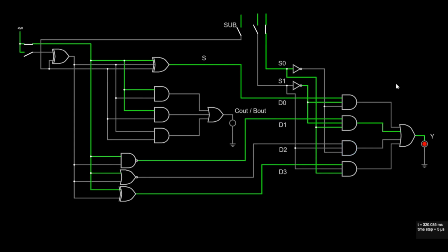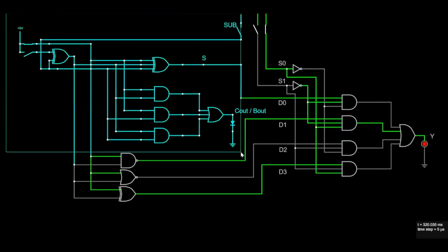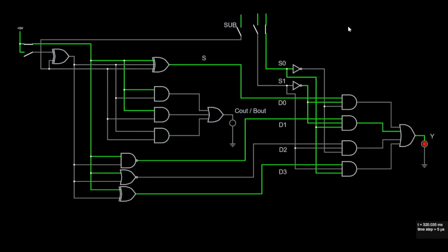And so we've seen some of these elements before, for those of us that are perceptive. We have a multiplexer over here, right? A 4-to-1 multiplexer. We have 4 data lines, one output. So we have a multiplexer. Big whoop, right? We've seen that before. We actually also have a full adder subtractor circuit right here. That's another thing we have. Isn't that crazy? The only thing we haven't seen is this circuit in this configuration.